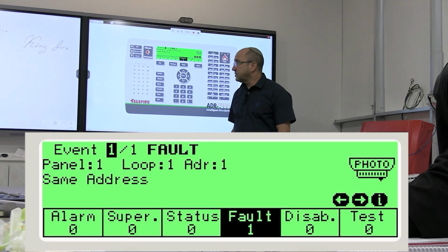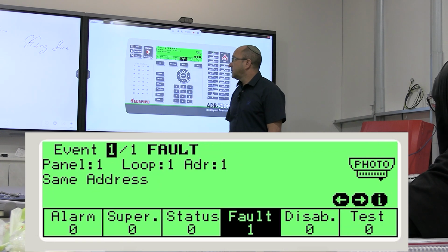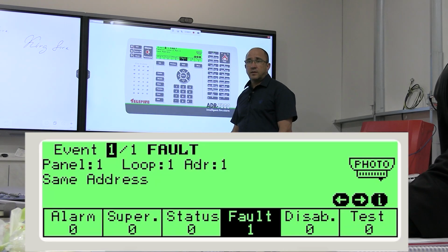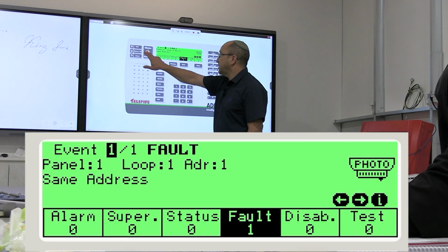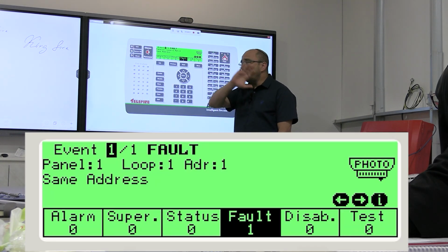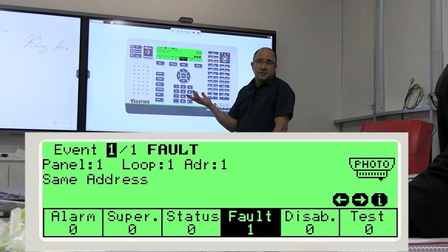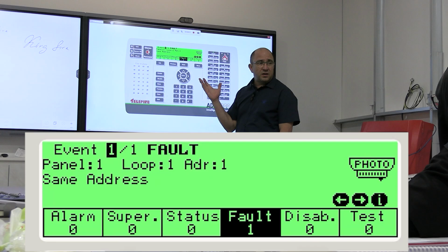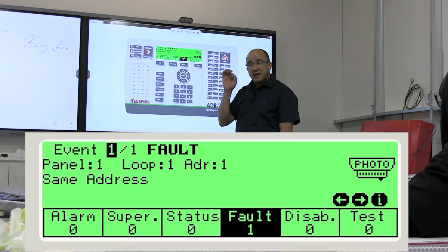I have a fault. Why? You tell me? Device not registered. No, it's written. You don't have to think. You don't have to maybe. What is the problem? Same address. That's it. Address number 1, same address.